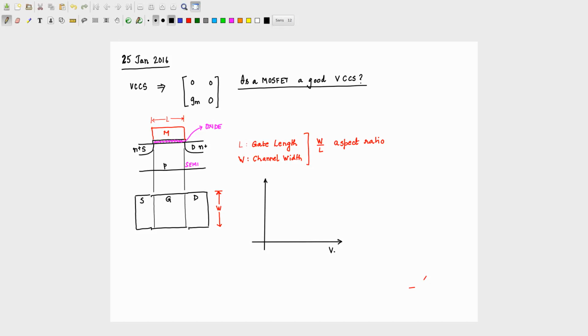The MOSFET we have discussed in the previous class has the following I versus V characteristics. Also, one should remember that we are interested right now in what are called the output characteristics. By output characteristics, we mean the following. We are interested in the situation where I plot VDS, which is the voltage between the drain and the source, on the x-axis, and look at the current ID. A symbol for the MOSFET, to complete the story, looks like this. The arrow is there, that is the gate terminal, that is the drain terminal.